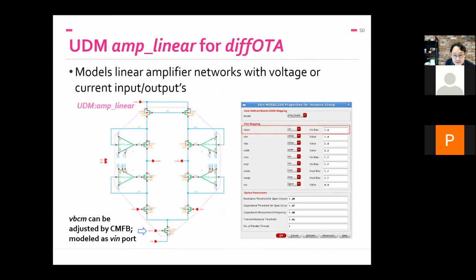So how do we model this? Well, again, it has multiple transistors, it has these sub amplifiers for boosted cascode, complicated. But we can map the whole thing, saying, hey, that's an amplifier. And it has an amplifier with 2 inputs and 2 outputs. So notice the multi-port amplifier model can have multiple inputs, multiple outputs. So it naturally extends to these differential OTAs. It can actually extend to other amplifiers that have auxiliary inputs, for example, for adjusting offsets.